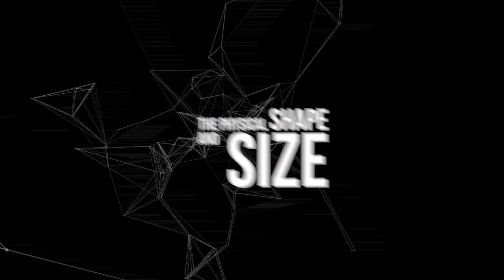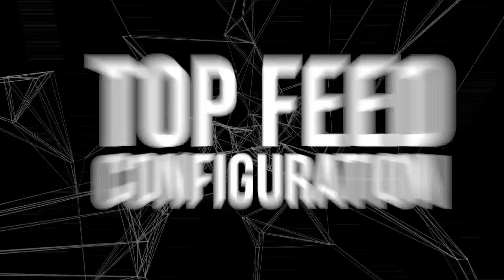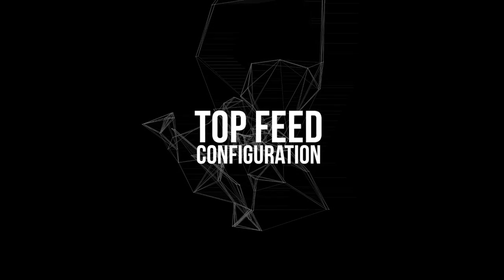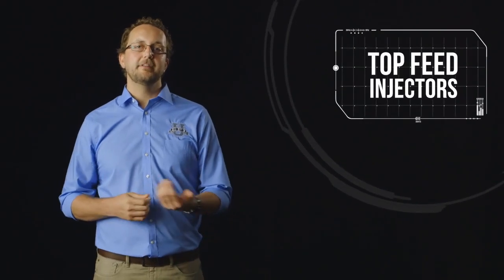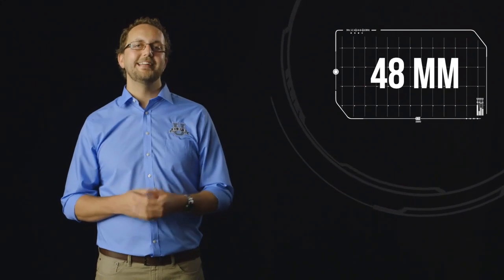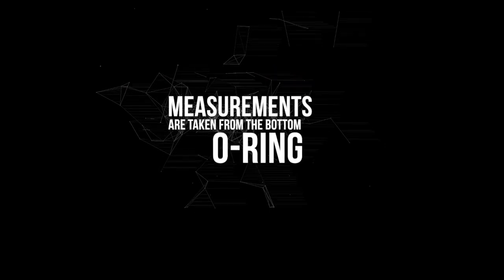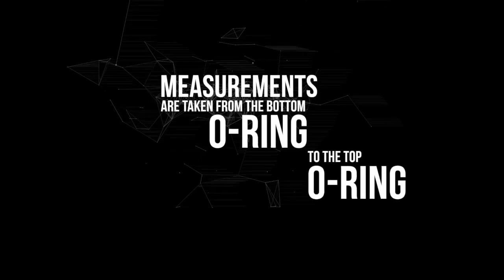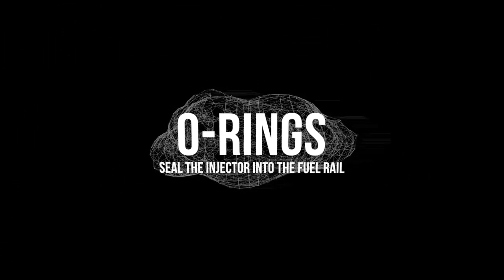The physical shape and size of the injector depends on the application. They're available in a top feed and a side feed configuration. Top feed injectors are typically more common and are available in a wide range of lengths, including 34, 48 and 60 millimeters. These measurements are taken from the bottom O-ring to the top O-ring. These are the O-rings that seal the injector into the fuel rail, and they're normally 11 or 14 millimeters in diameter.